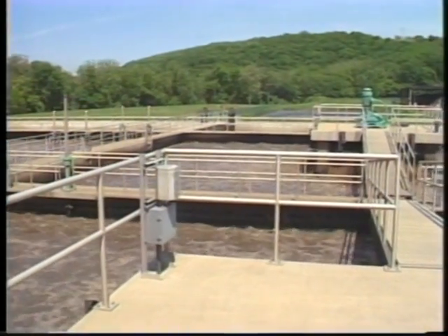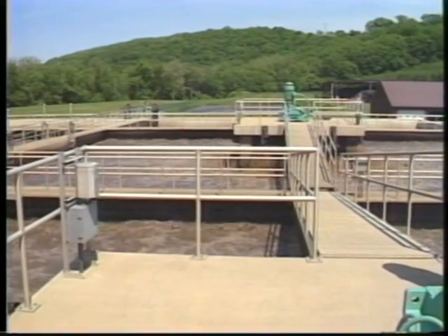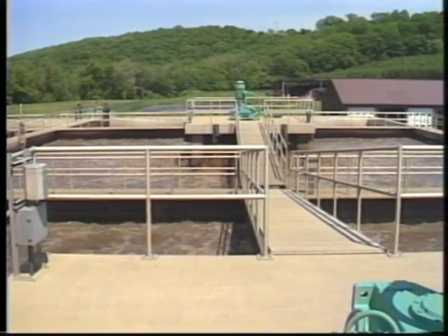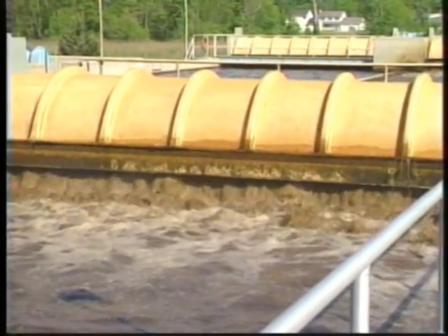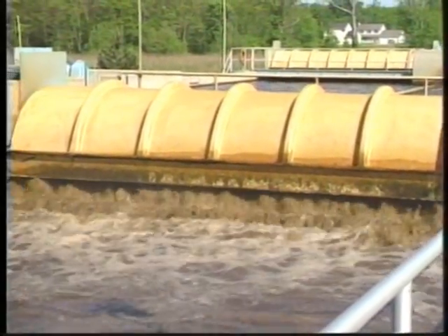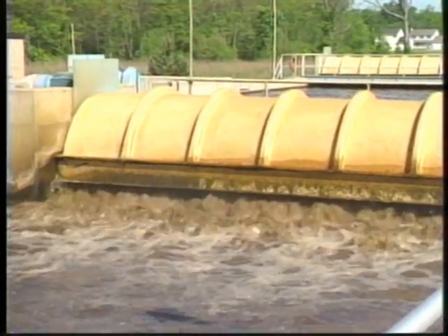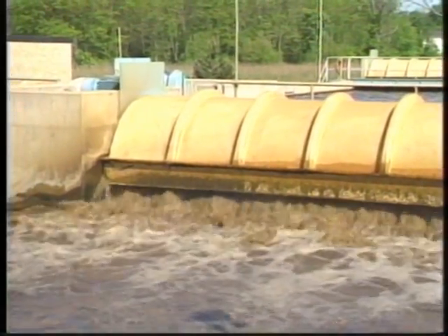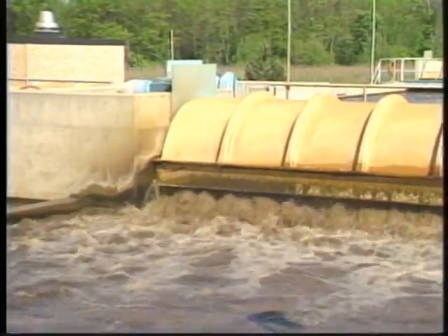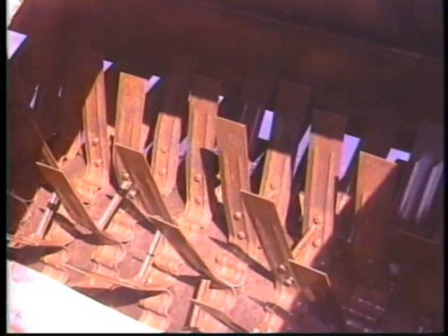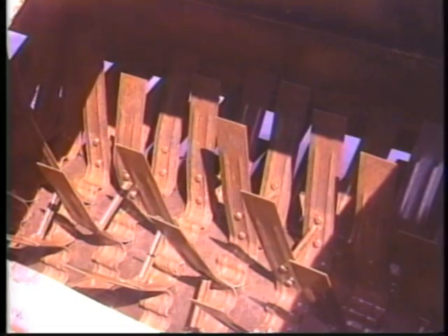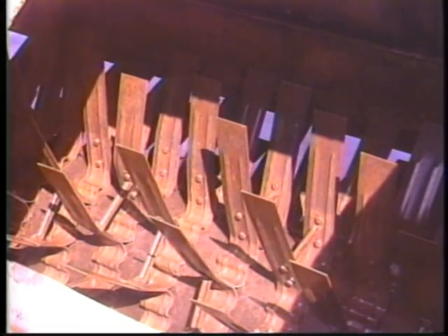With this flexibility, you may be able to treat peak flows or higher loadings at your facility in the contact stabilization mode. The oxidation ditch is another variation of the activated sludge process that is usually operated in the extended aeration mode. This system utilizes a continuous loop type of tank with a rotor. The rotor is a mechanical device that includes a shaft with many paddle-type blades on it. The purpose of the rotor is to mix the contents of the tank and to transfer dissolved oxygen into the